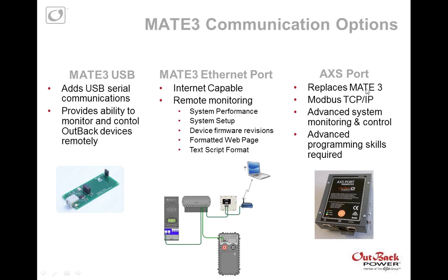However, the next level is the Access Port, and this replaces the Mate 3. It uses a protocol called Modbus TCP/IP. It is an advanced system monitor and control. It gives you a lot of power in the system and you can do a lot of things with it, but it does require advanced programming skills. You really need to be a professional programmer that knows C++, Python, or some advanced language. You need to know Modbus TCP/IP, not just Modbus RTU, the SunSpec specification, and you need to know networks, especially your local network. So it's not trivial, to be real honest with you. But people who live in this world, especially up in Canada in oil and gas areas like Calgary, which have big SCADA systems, will be able to handle this kind of thing. But this is not your homeowner, this is your industrial customer.